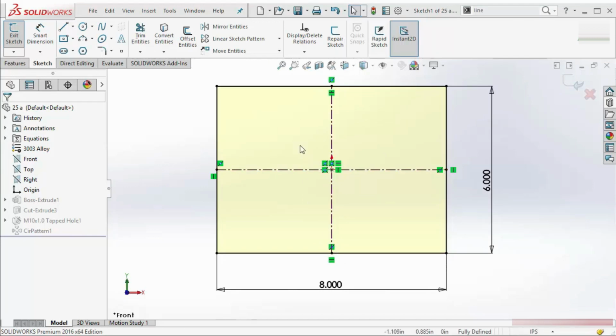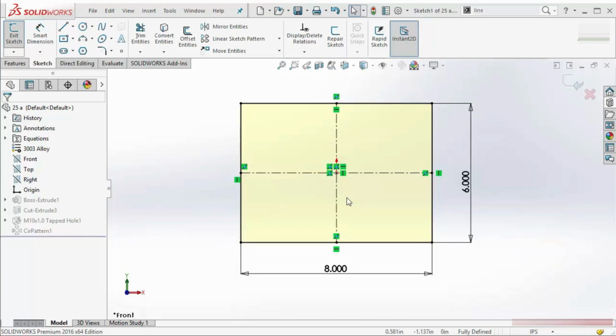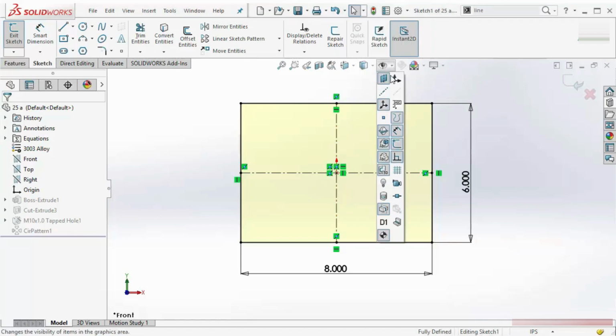You do not need to understand too much at this stage. When you create a very busy sketch, the number of these green icons will increase drastically. In that case, you have to hide it. You can hide it very quickly. If you go to this drop down menu, from here this is showing view sketch relation. If I uncheck this, it will not show you again.